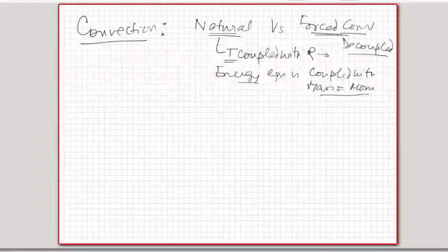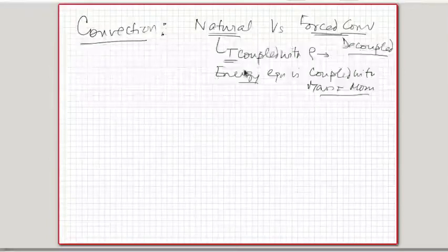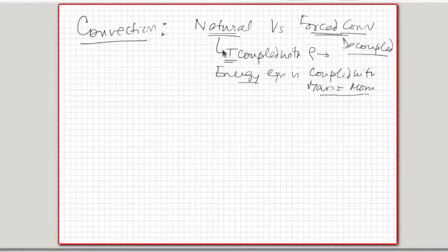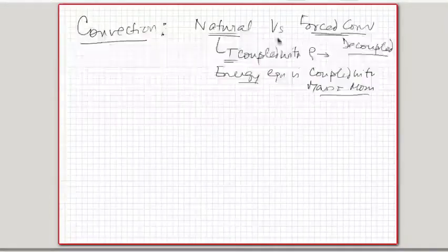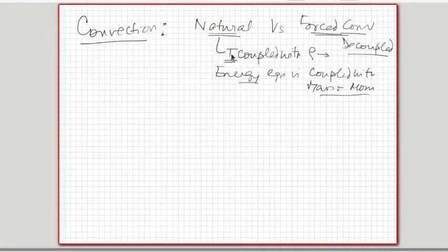So forced convection problems are easier to solve than natural convection, because you can solve for the fluid flow independently and get the velocity and density distributions and use that as an input to solve the energy equation, which is linear. Okay, so that is a simpler thing that happens, but in natural convection the coupling is important.